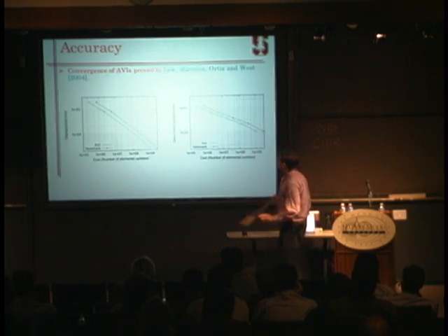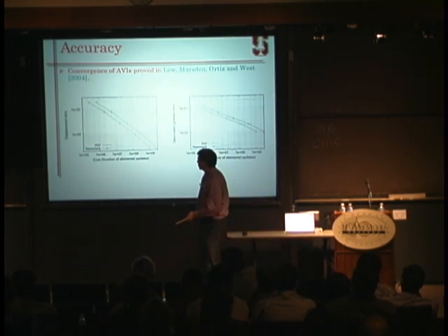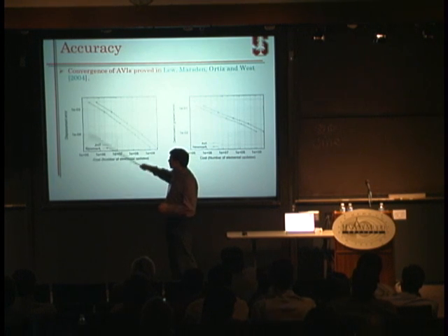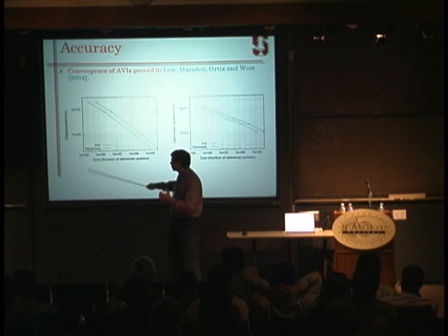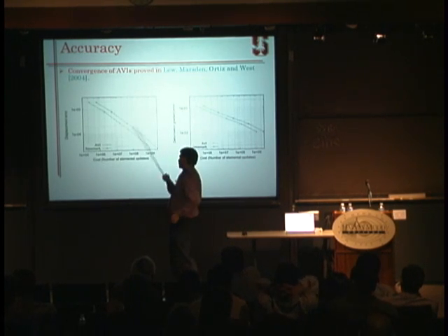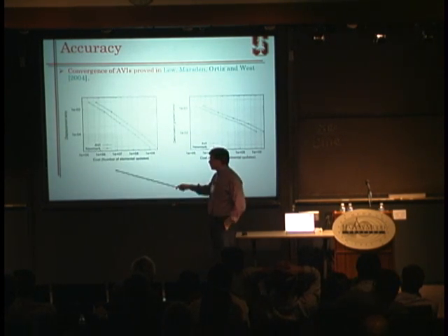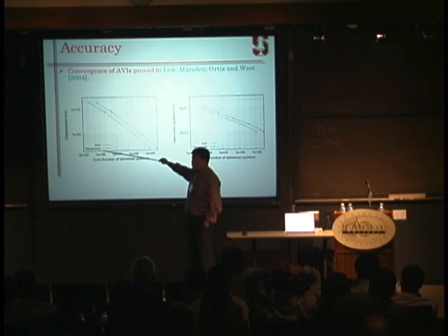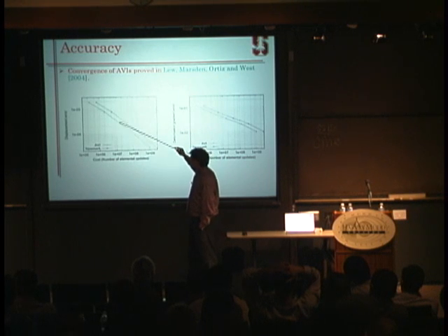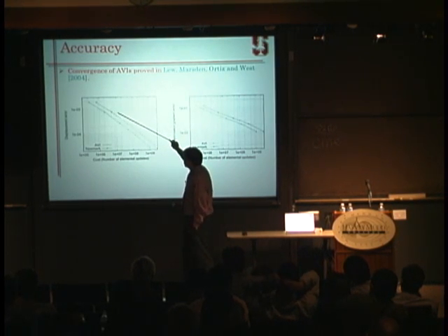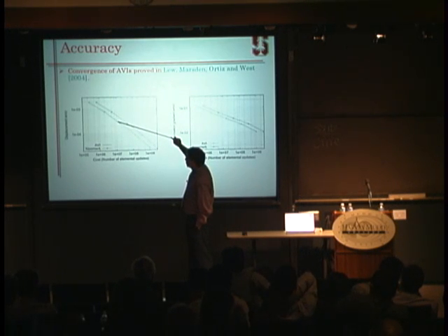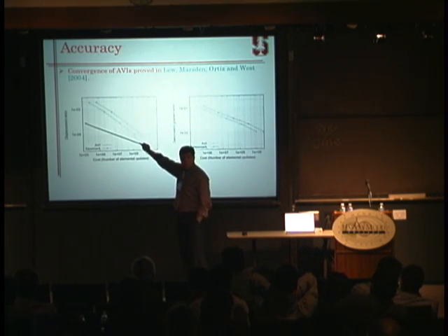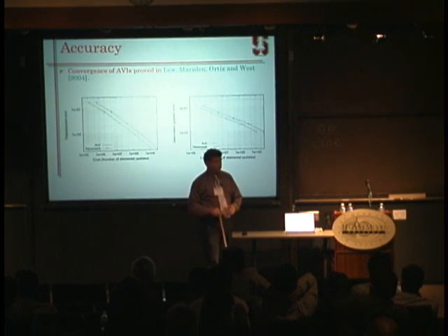We also prove the convergence of these algorithms. Here, for instance, is an example: the plot of the L2 norm of the displacement error as a function of the computational cost, using synchronous integration or asynchronous integration. Okay, the same problem. So this is the synchronous curve. This is the AVR curve. So for a given computational cost, you get a more accurate solution using asynchronous integrators.